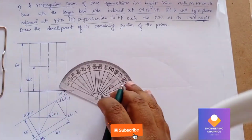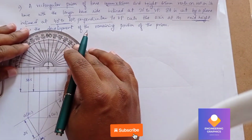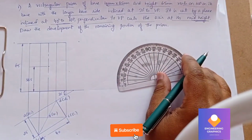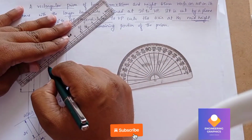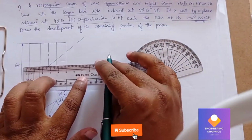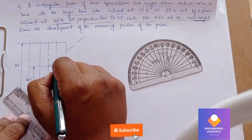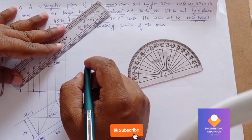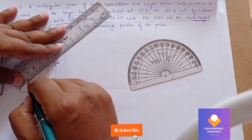Now we have to take the protractor and mark an angle of 40 degree at this reference point. Mark the angle 40 degree and draw an angle line passing through this point. So here we will be constructing a section plane. We'll extend the same thing. So we can show the angle here first. The angle is 40 degree. So we'll extend this section plane for the downward side.